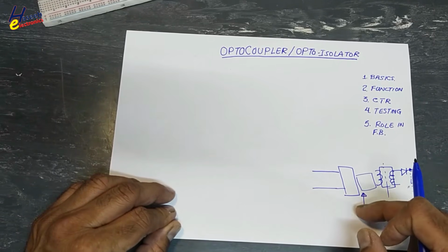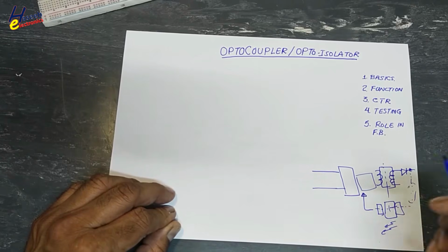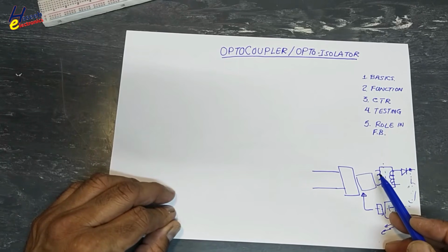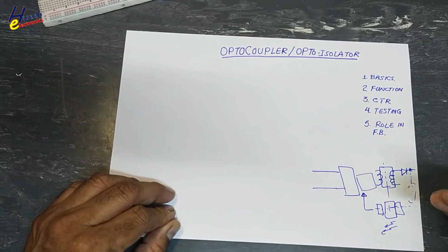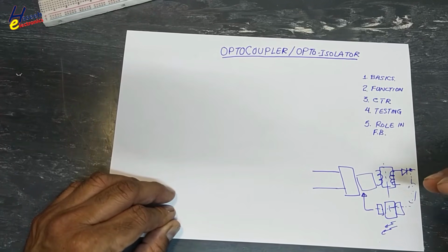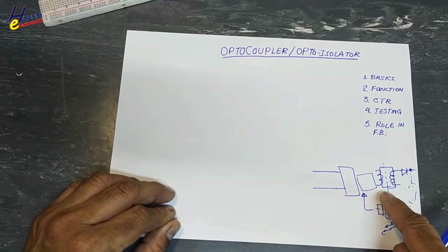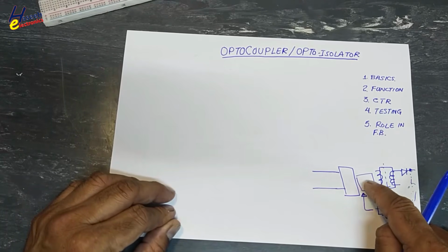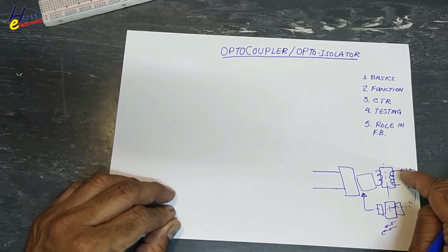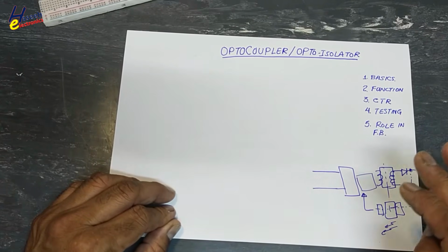This smart switch will decrease its switching, decreasing its magnetic flux in the primary side. As a result, output voltage will decrease. If the output voltage is decreasing, it will give feedback that the output has dropped. So it will increase its magnetic flux by increasing its switching cycle so that output voltage will be maintained.